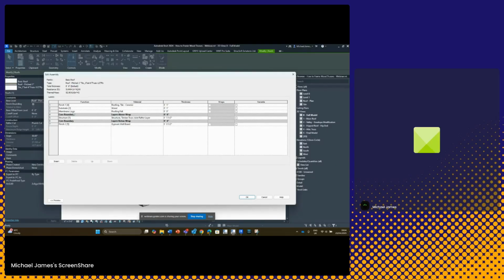Our framing members are then placed after our membrane layer, which has 0 thickness. So what I need to consider right now is the 2 inch layer that we need to leave free for the substrate for our wood battens and our roof tiles in this case. So I want to place these structural framing members 2 inches from the top. We'll bear that in mind when I start framing and it will make sense.